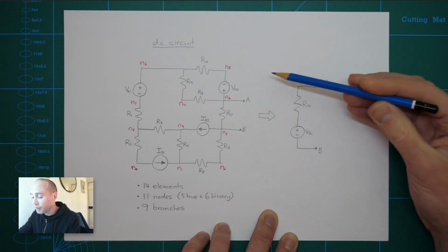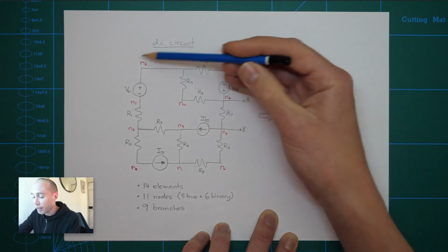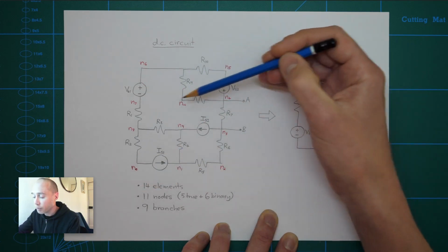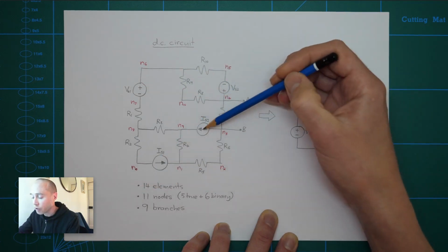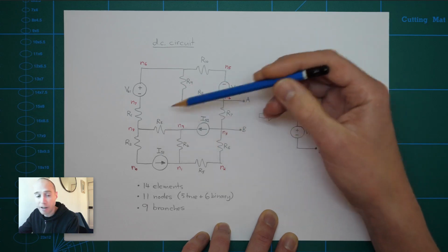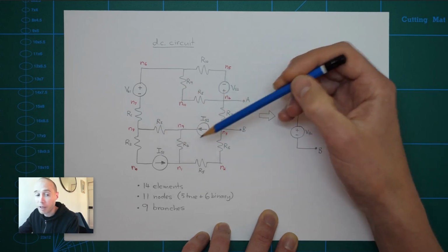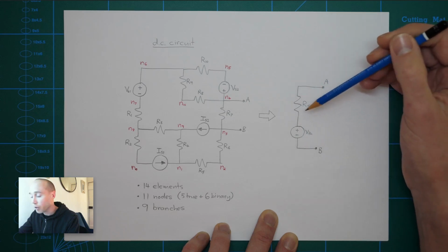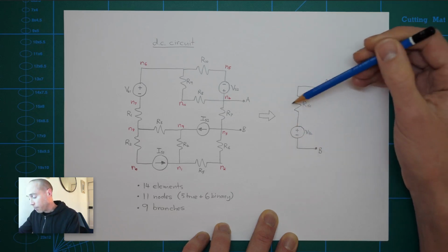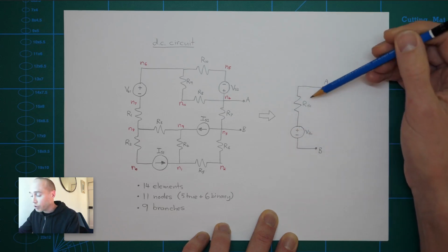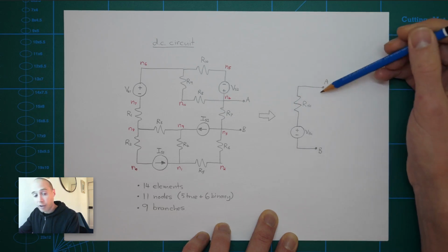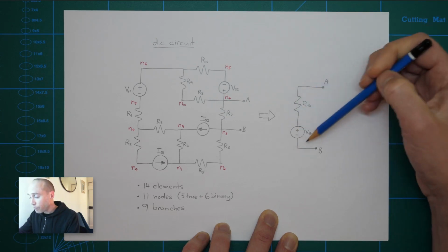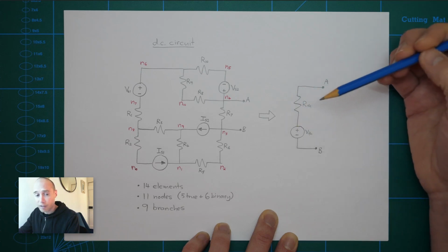So for a DC circuit, anything inside the box, as long as it's made up of just these voltage sources, current sources and resistors, no matter how you connect them together, no matter how many of them there are in there, it can always be replaced by this much simpler equivalent circuit, which from the perspective of an observer at AB behaves electrically the exact same.